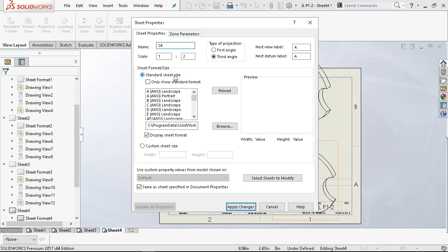I don't need to add anything else, or if I do, I'll add it later because I needed it there. And it just so happens to work out that somewhere between 2 and about 20 parts in a subassembly is kind of in that optimum range. A drawing package with 2 to about 20 sheets is about all you want to manage. So there's a point where you'll hit that mark and find out that it's pretty good.